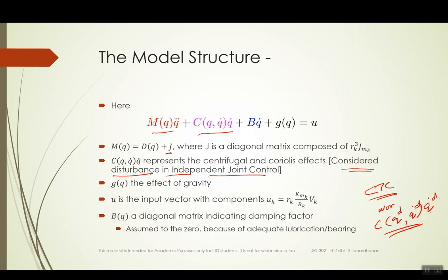Okay, so in this lecture we will ask: is there a simpler control than the computed torque control that does not ignore the Coriolis force and still gives performance?